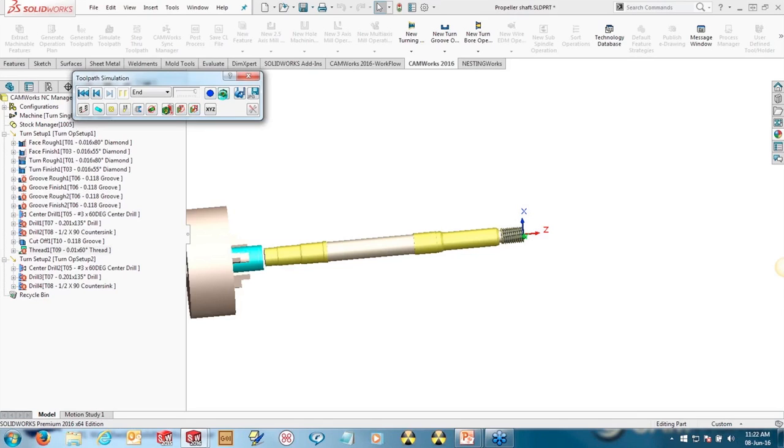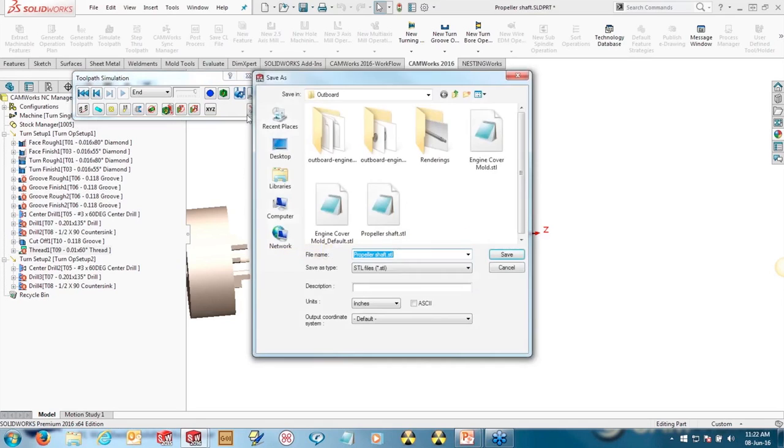Basically, what we can do, obviously, you can compare the toolpath over here and see what the actual program cuts versus what the finished part looks like. But obviously there's this chunk of material at the end that the cutoff basically took away. So we don't want that. We can go in and just basically get rid of that. And we can save this to an STL file to use as the input as the stock on the mill. So I'm just going to switch it to save out to the mill coordinate system. We'll leave it set to that same name here.